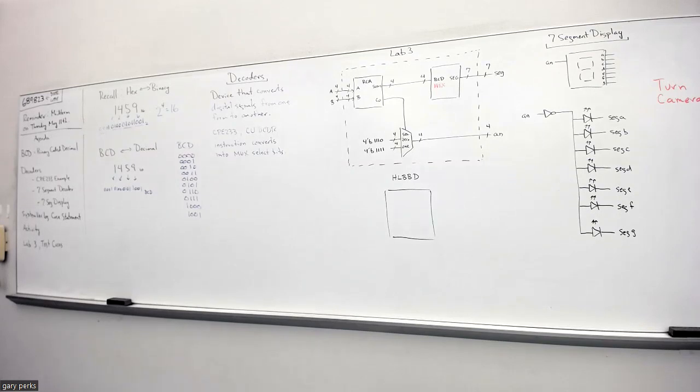The ALU fun goes to the ALU, which, when you take that class, you'll learn is basically a big mux that can do mathematical and logical operations. ALU source B is the select to the mux at one of the inputs of the ALU. The ALU source A is the select input to the mux that connects to the other input of the ALU.